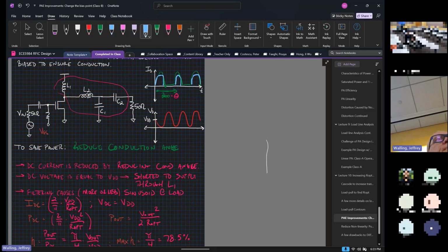Yeah, but that would happen to the Class A as well, right? Sure, it does. But with Class A, I'm still getting 360 degrees of swing. This can be qualitative. We'd have to drive the two into saturation. I would argue that most of the time, the distortion is going to look worse for the Class B amplifier, but you're right, it could be otherwise. There are cases where I might drive the Class A with an impedance that causes it to be a disaster. Well, I'm specifically wondering about intramod, not necessarily harmonic distortion. But yeah, I'll look it up first.